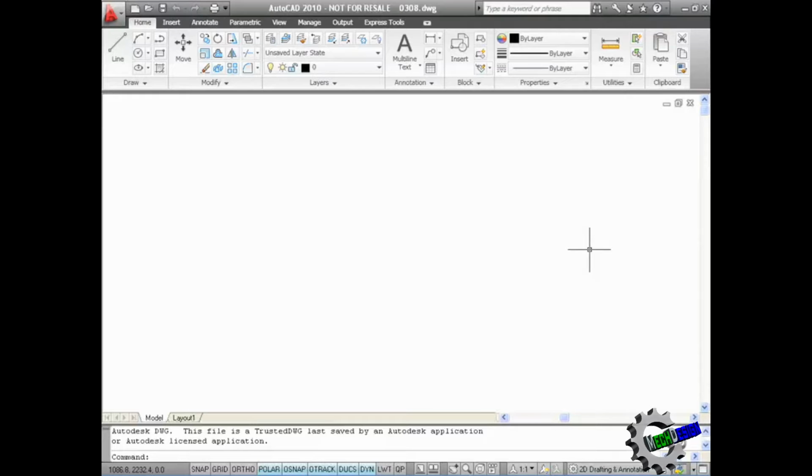That is actually wrong. There are text styles, blocks, dimension styles, multi-leader styles. These can all be in a drawing, but they might not have been used to actually place any objects on the drawing. Also, if you look at your layer pull down here, you'll see there's a layer called Objects. It's yellow and we have a white background. What that means is that the yellow objects might not show up as well as a red object, for example.